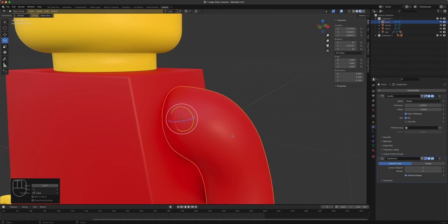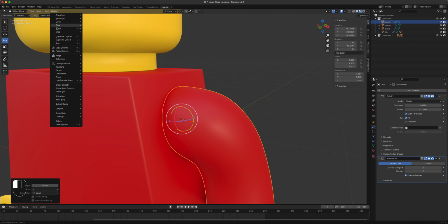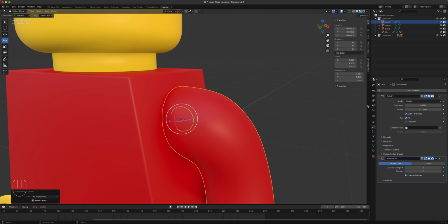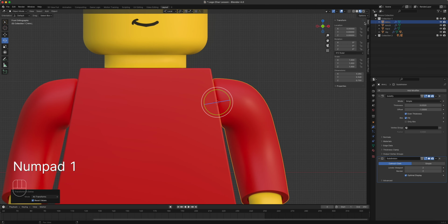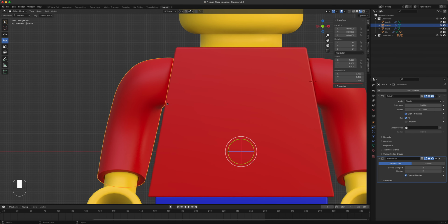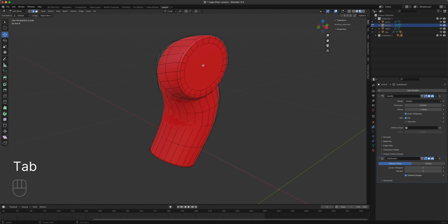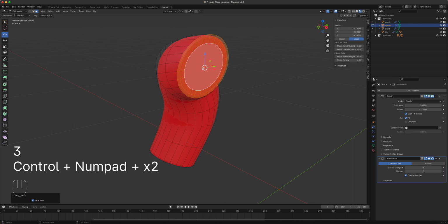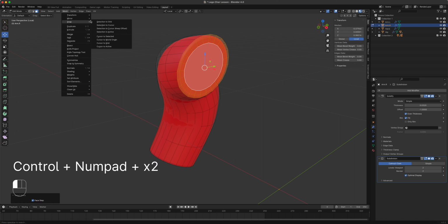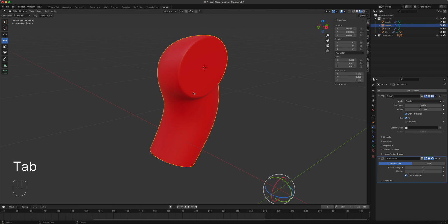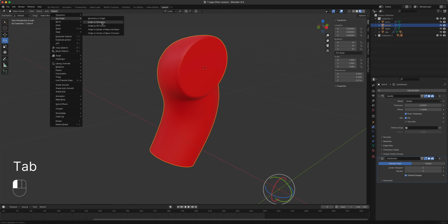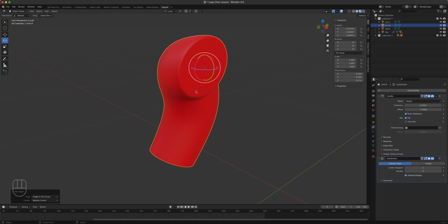But before I do all of that stuff, I forgot, I have values here. We can go here, Object, Apply, Transform Deltas, so that it zeroes out everything. Okay. So let's do the exact same thing here. Let me repeat all that process. We select the face here, and then we tell it to snap cursor to selected. Go to object mode, set origin to 3D cursor, and now this is set.